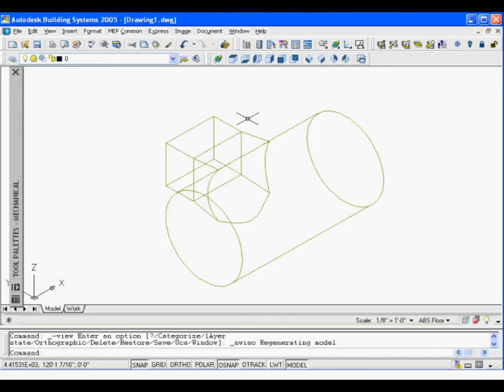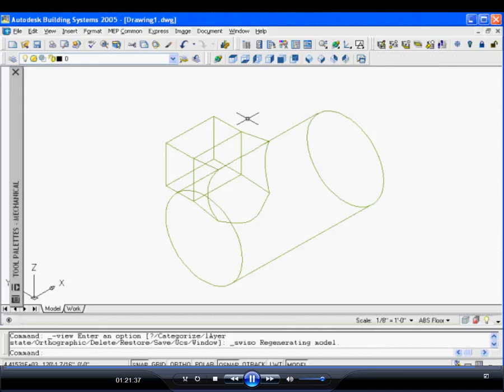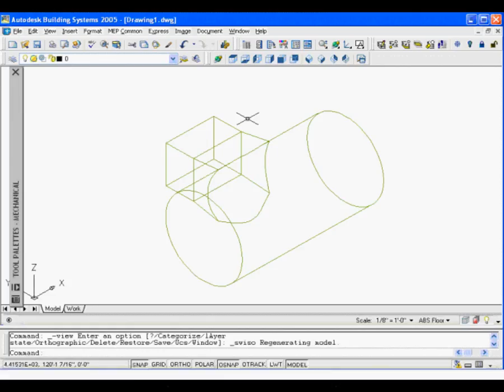The other way you can also do that is when I added in my values, I used list for my values. I can also use table. And what table will allow me to do when I define the different part sizes, it will allow you to develop a table based on the available size options that you have. That's another way to do it if you don't want to put a physical constraint in, is you can use a table and lay out all your different part sizes based on that information in the database.